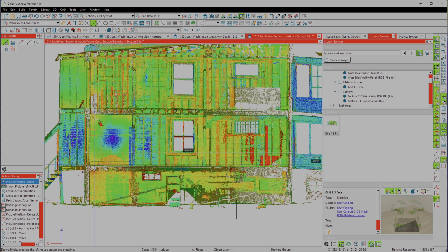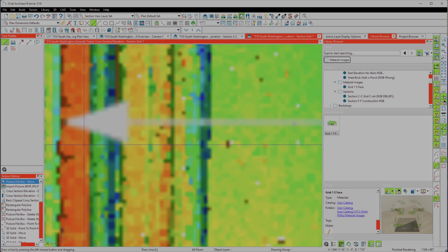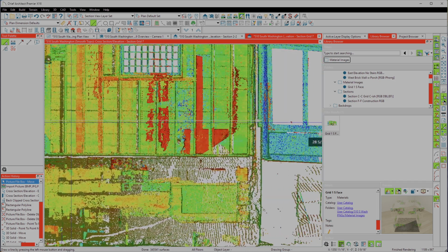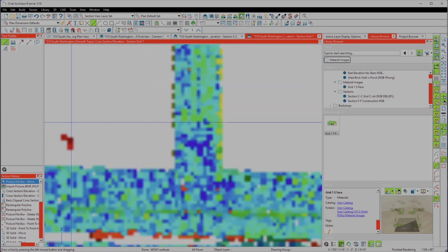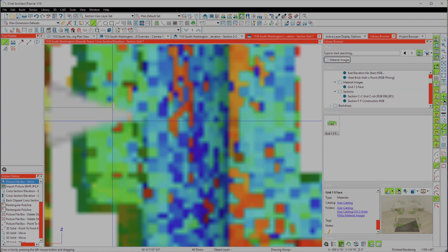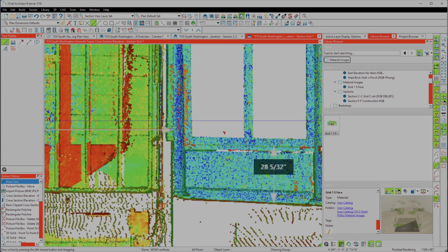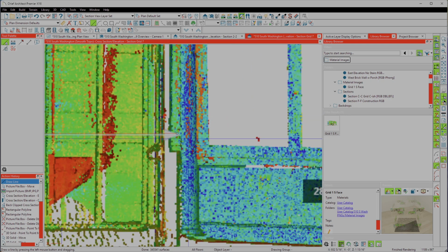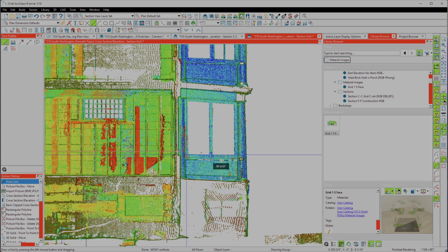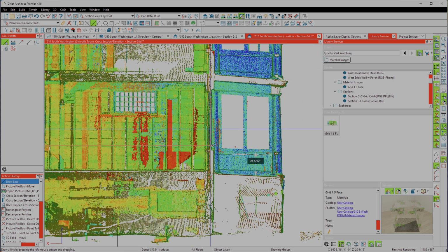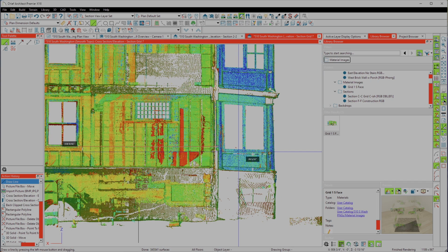So I'll go to my line tool, zoom in, and I have a 3D Connexion mouse, so when you see me do some pretty interesting movements, it's because I'm using it to come in and zoom back into the end here. It's obviously not perfectly straight level, but that's because when you're doing a point cloud, you're grabbing points in the cloud, and even in that dimension, I can't say it's given me a great ending point, but somehow I grabbed a point and we called it good.